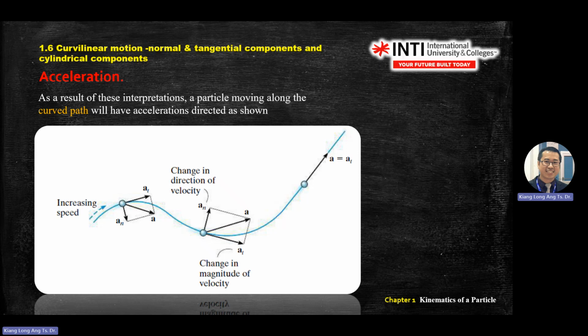One careless mistake is this one. When the question simplifies until the particle moves in a straight line, there is no normal acceleration. You only have a_t acceleration. Take note on this one. If you're taking notes, put many stars here. When it comes to the exam, you will get confused. You will try to flip, you will try to create a normal here. No normal. If you move along the path, you only have the tangent component.